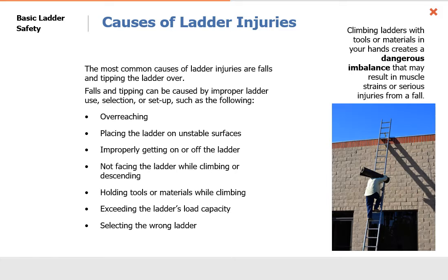The most common causes of ladder injuries are falls and tipping the ladder over. Falls and tipping can be caused by improper ladder use, selection, or setup, such as the following. Overreaching, trying to get that one extra tool or finish one extra job when you're not in the proper location.